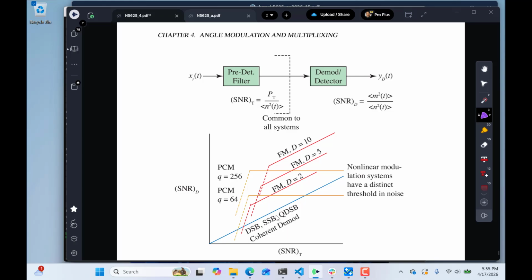If you're listening to AM radio, let's say, driving from here heading towards Kansas, you can listen to the strong signals from Denver just gradually fade away as the signal gets weaker. It gets down into the noise more, so that's this vertical axis, whereas the digital schemes and the FM schemes drop out. When you hit a certain radius, you're below threshold and it's just gone. So that's a phenomenon there with the modulation types.